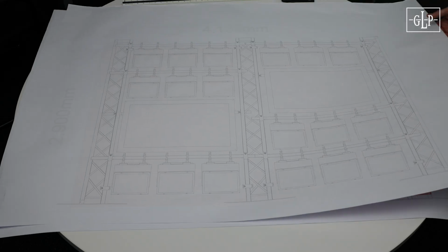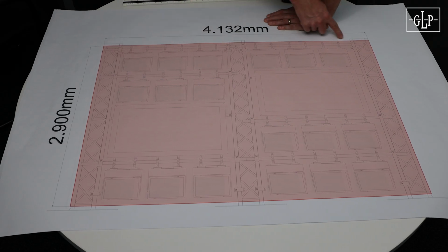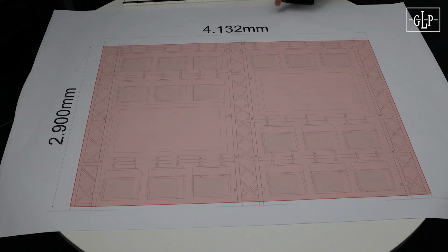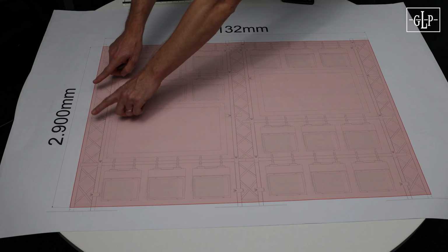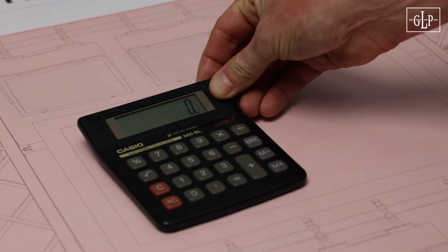According to the chosen origin, we now set the canvas size across the entire width and height of the setup. We now determine the exact width and height in millimeters from the software itself or from the construction plans. In our case, 4132 mm width and 2900 mm height. To convert the physical dimensions into pixel resolution, the length in millimeter is divided by 7 mm pixel pitch of the JDC2. This results in the following calculation.